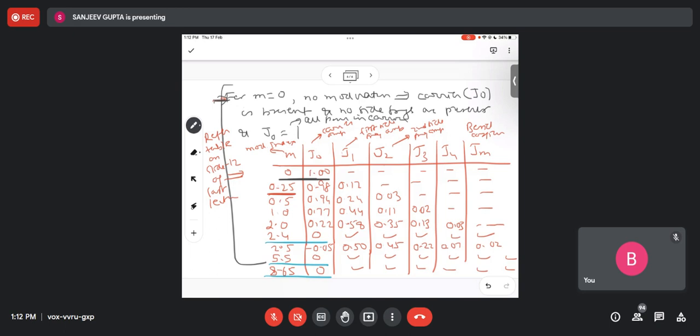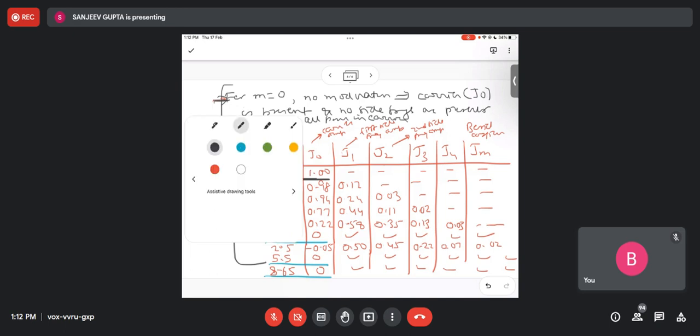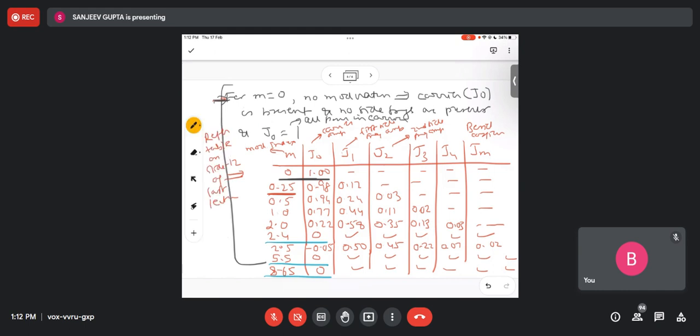And there is another case which I am highlighting in a different color, which is this one. That means 0.25, if I say the power is in the carrier and the first two side frequencies, and no other side frequencies exist. That means for m equal to 2.5, it is closest to the AM modulation. So it is just like your AM.